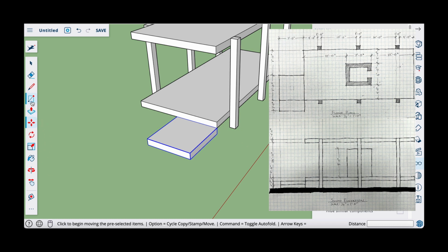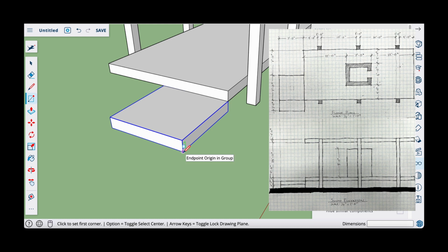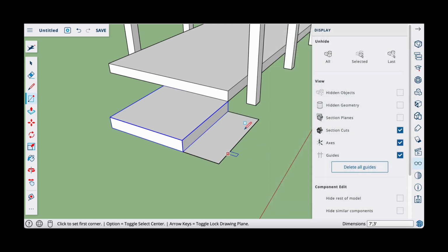I'm just going to use the rectangle tool and click right here, click and release, and then move my rectangle tool in this direction, and I will type 7 apostrophe comma 3 apostrophe because I want the other corner to be 7 foot in the X and 3 foot in the Y. And now I'll just push that down, push pull tool, 1, 2, enter, because it's 1 foot thick. And now I'll select all the geometry, triple click, right click, make group.